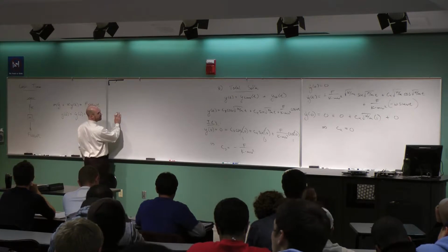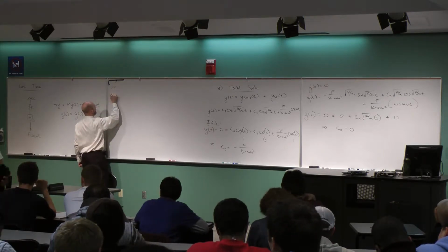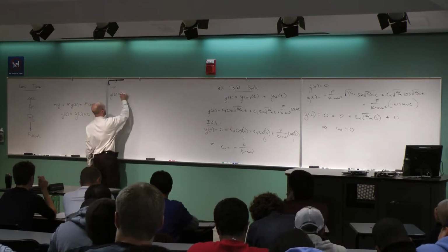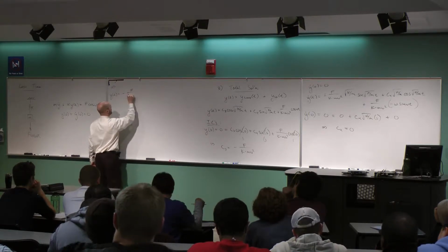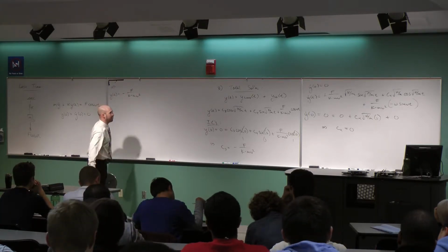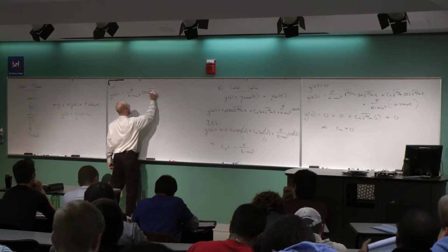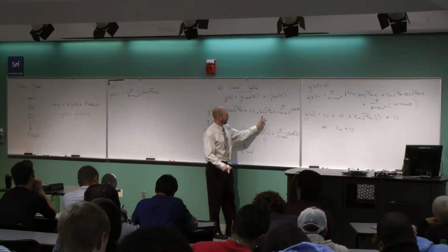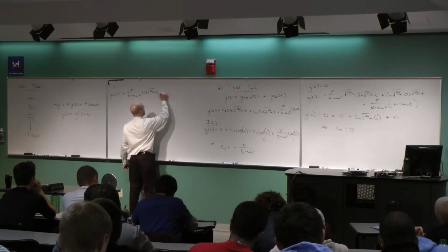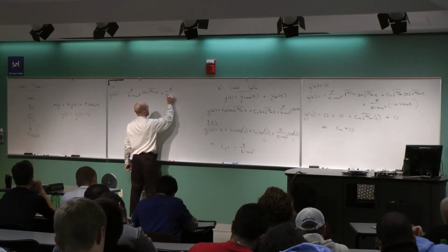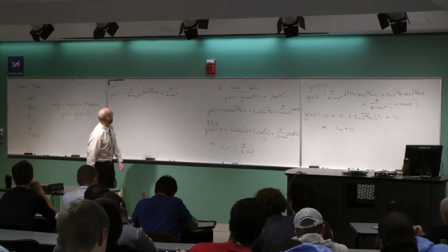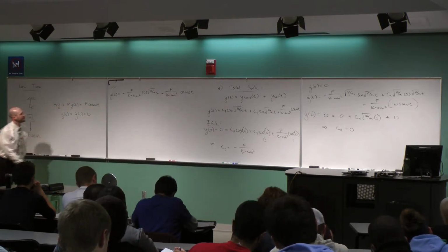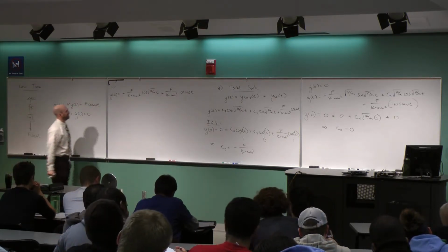So finally, the final result is y of t is going to be C3 cosine root k over m t. There's C3 minus f divided by k minus m omega squared. That's C3 cosine root k over m t. Right? The C4 is 0 plus 0, and then I have this term, which is again the same thing, f divided by k minus m omega squared. But now it's a different frequency. It's the cosine of omega t. Can I do anything to simplify this algebra?